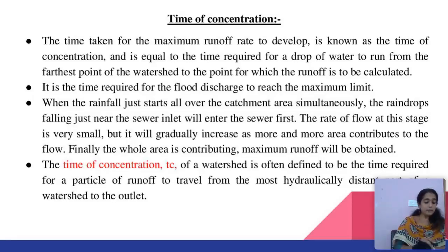And the third point is the time of concentration, Tc, of a watershed, which is often defined to be the time required for a particle of runoff to travel from the most hydraulically distant point of the watershed to the outlet. This is the time of concentration.